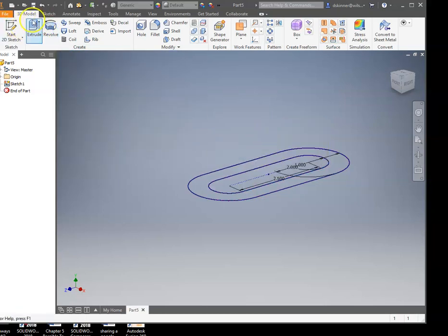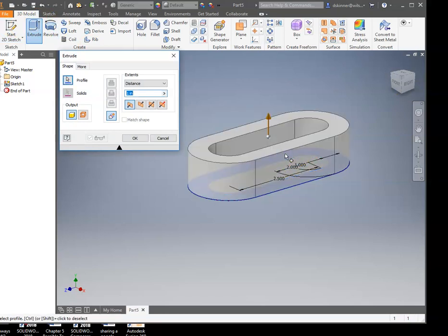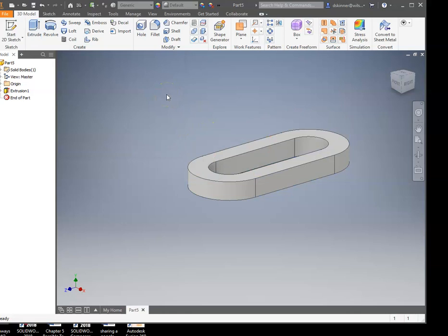So I'm going to click on extrude again, and this time I'm going to choose, and you see there is only a subtle difference in the gray color. Click on that, and then it is extruded 0.5. Can't read that very well, but that's extruded 0.5, and I went ahead and hit enter, and it took me out of that. So you can see I pretty much have that basic shape, but this is cut out